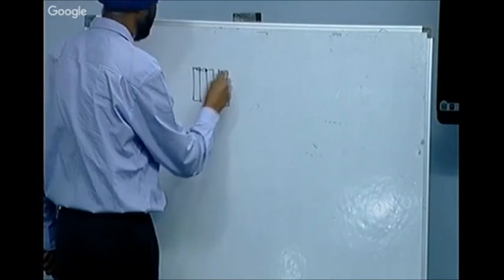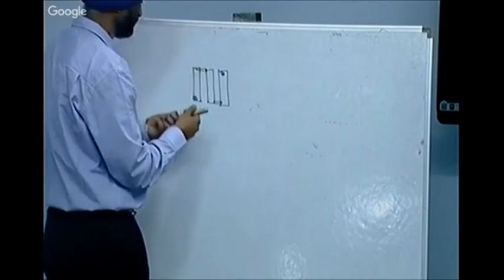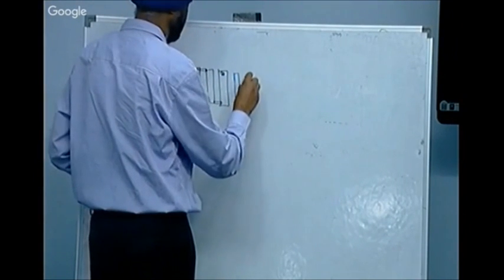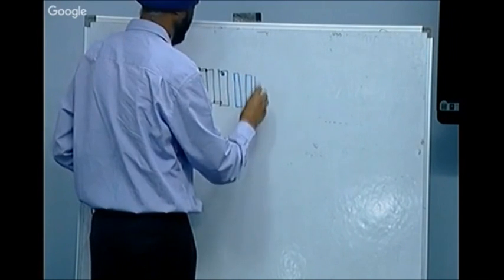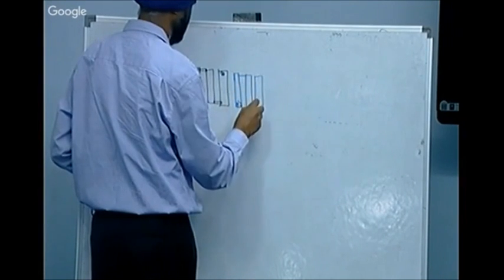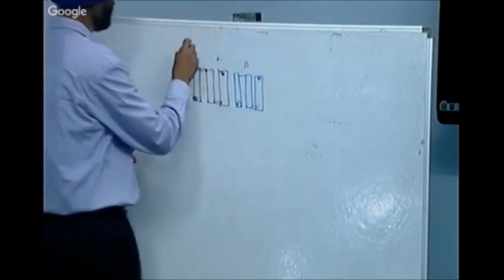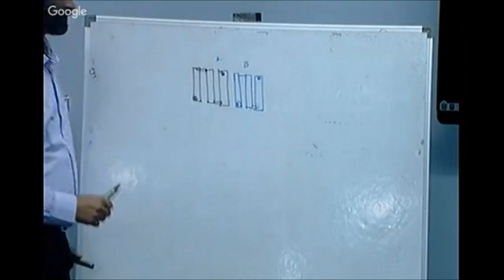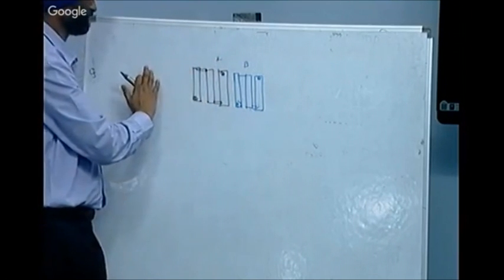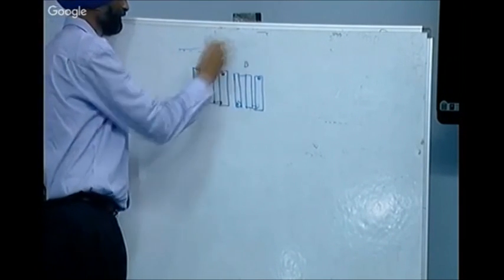Now you are taking this resistor, so one, two, three. This is one resistor A. Another resistor you have placed here, which is B. Normally in a wafer, when you manufacture, there can be some process gradient. Like if we are doing some implant, some dopant, if it is uniform, it does not matter. But sometimes a gradient is there.